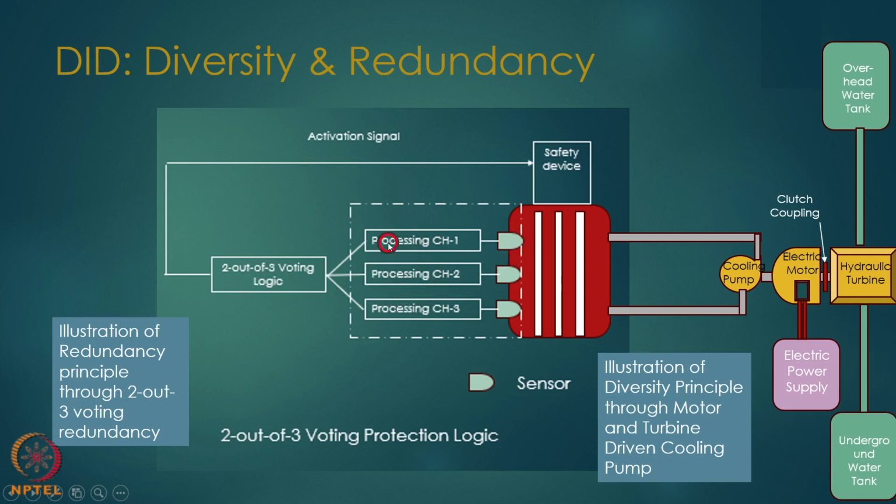We required 1 sensor, but we have provided 3, because it is called system resilience, or having embedded capability in terms of safety. It works for reliability also. For example, if you want to carry out maintenance, I can take out 1 channel for a short duration and perform maintenance on it, while the other 2 channels keep the plant operating. This is a regular practice in the plant. The technical plant safety document allows you to take it out only for a certain duration and then put it back in service. This is an example of redundancy that we discussed.